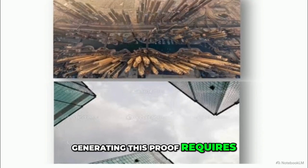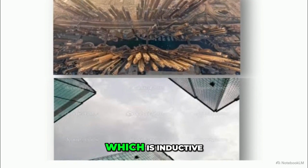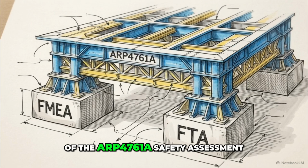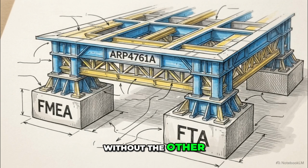Generating this proof requires two orthogonal lenses: failure mode and effects analysis, which is inductive, and fault tree analysis, which is deductive. These two methodologies serve as the dual cornerstones of the ARP 4761A safety assessment. Neither can guarantee safety without the other.